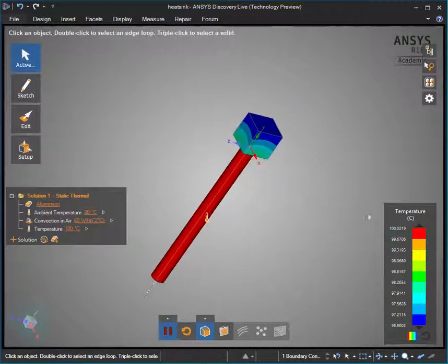So we're already getting visual feedback in terms of the heat temperature over here, the coolest being on the very top of the cube, like we might expect. Also, how it knows what that temperature would be is based on the conditions of the ambient surroundings. By default, it's got the room temperature set to 20 degrees Celsius, which is pretty standard. We could always adjust this value, and also the convection in the air. So it's not just losing thermal energy through radiation, but the convection value here we could later go and adjust if we wanted to make it match different conditions.